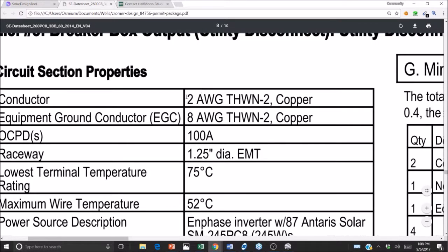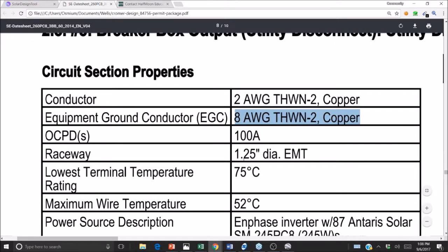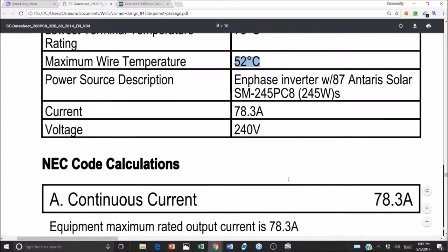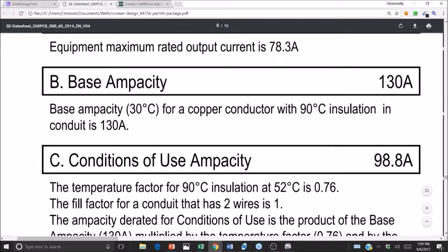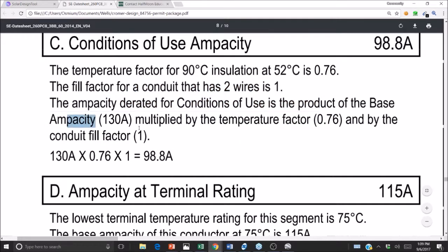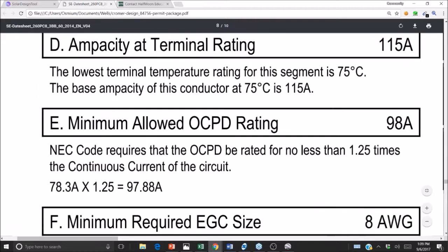And what we see is that our equipment ground conductor is undersized. And we see our conduit sizing. And what we'll see in the next couple of sections of code under the general sections, that's all in sections 200, 300 and 400. So we have the 90C conductor derate factor, the fill factor, the output ampacity adjusted for temperature and conductor fill.